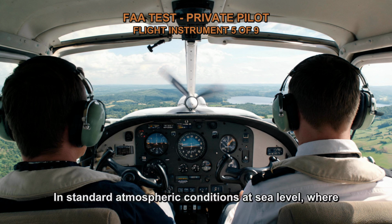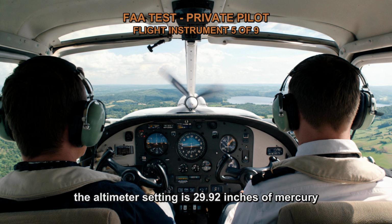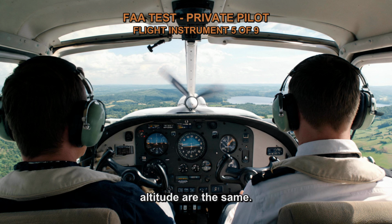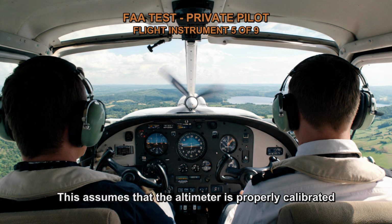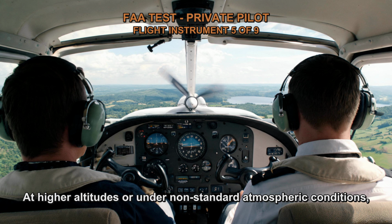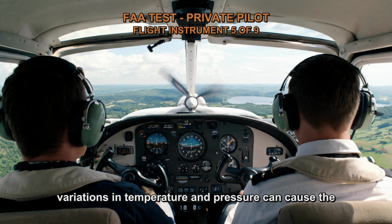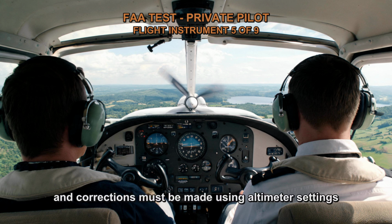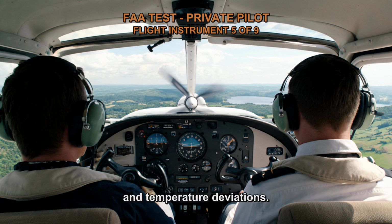In standard atmospheric conditions at sea level, where the altimeter setting is 29.92 inches of mercury, or 1013.2 millibars, the indicated altitude and true altitude are the same. This assumes that the altimeter is properly calibrated and free from any mechanical error. At higher altitudes or under non-standard atmospheric conditions, variations in temperature and pressure can cause the indicated altitude to differ from the true altitude, and corrections must be made using altimeter settings and temperature deviations.